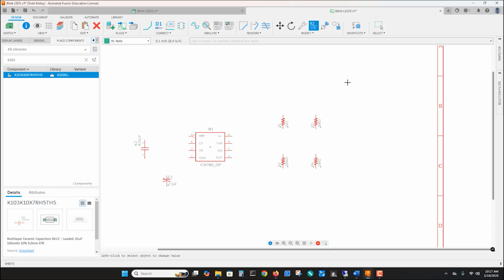Okay, we need some kind of power to power our circuit here. And what I've decided to do is we're going to actually put a USB-C connector to supply power to our circuit. And I found something on Adafruit that is literally just a USB-C power-only connector. The item number is 4907. And there is a link to the library in the description and on our GitHub page. So we're going to add the USB 4125 to the library and place it instead of a full USB-C connector.